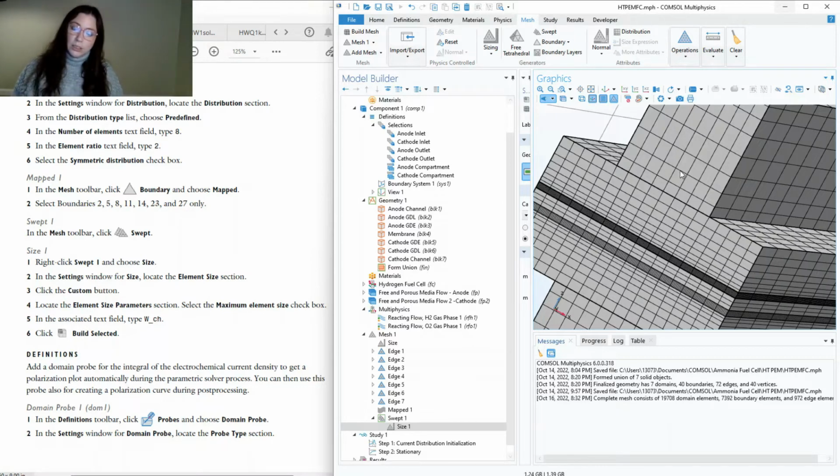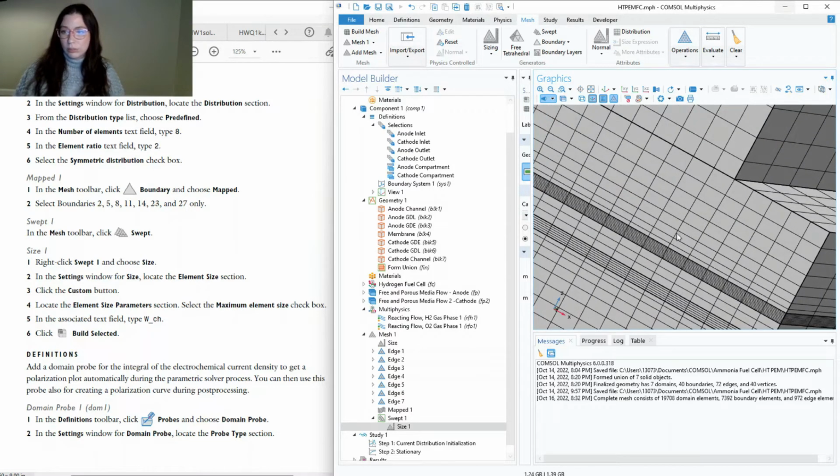So let's say you're using ammonia and it decomposes into hydrogen. Well, now you don't have an excess of hydrogen. Most likely that process would not be reaction rate limited. It would be mass transport limited or diffusion limited, because then you're talking about the decomposition of ammonia, and the presence of the hydrogen that has decomposed from the ammonia serves to inhibit further decomposition of ammonia. So it will drastically reduce the readiness of available reactant there.